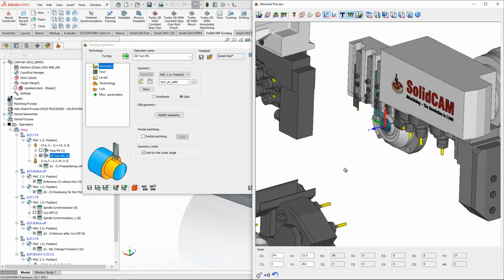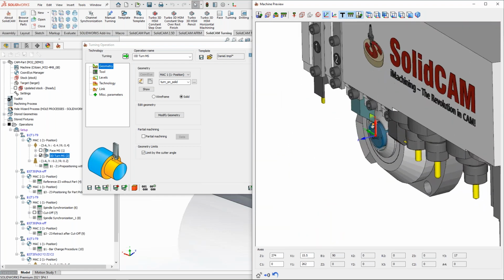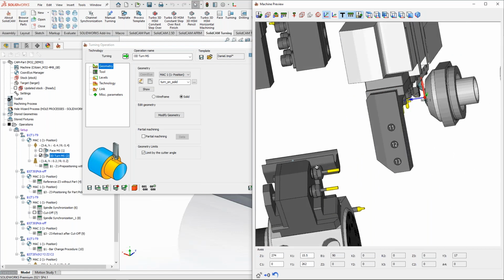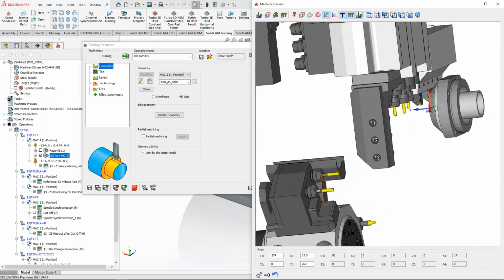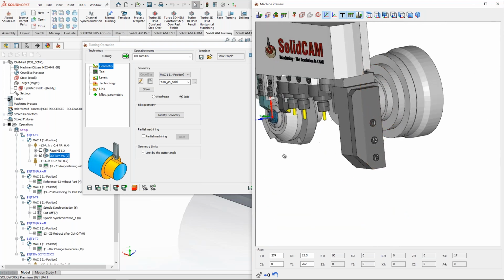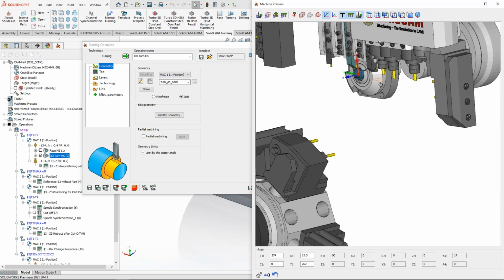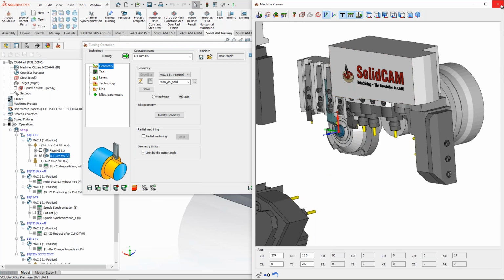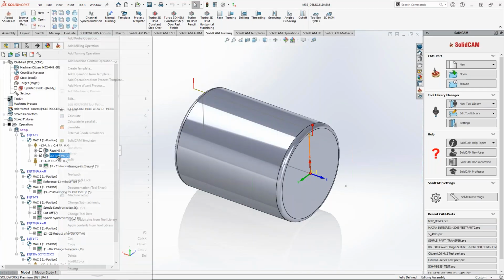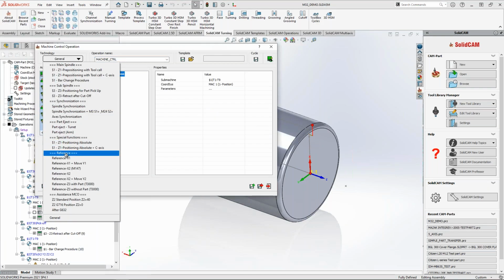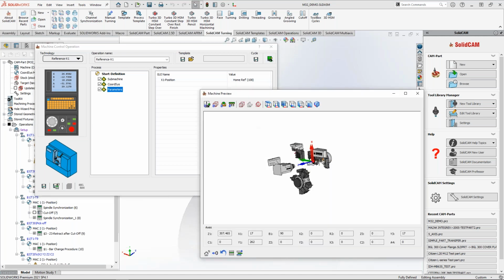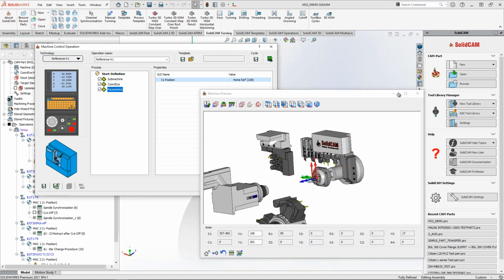And I want in this demonstration to use the C-axis, just interpolate over this bar, nothing so special, just to get some toolpath. I want to show you the example, and for this I'm going to use this tool over here. But before I do that, I will probably have a collision once it approaches, so I need to make sure that the turret is in retract position. So I'm just going to quickly do that in the home reference. Great.